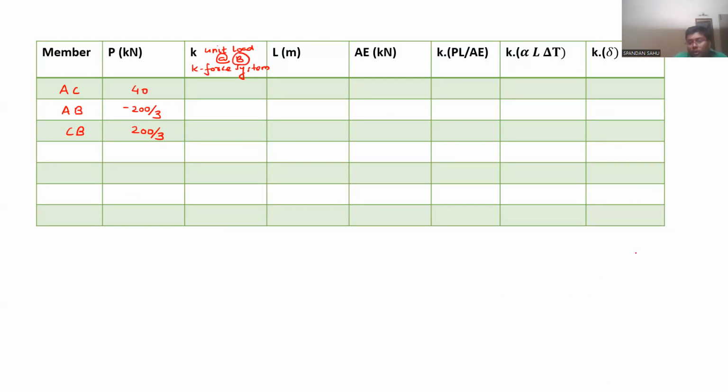So it will be something like this. We need to calculate the vertical displacement. So vertical unit load at joint B, this is joint C, this is joint A. In joint A, there is roller support. So this will be Ax. At C, the support condition is a hinge support condition. So two reactions, Cx and Cy. What else? That's it. This is the free body diagram.